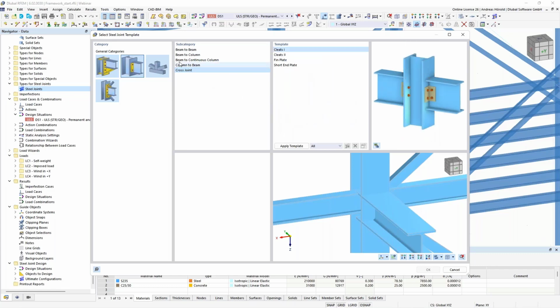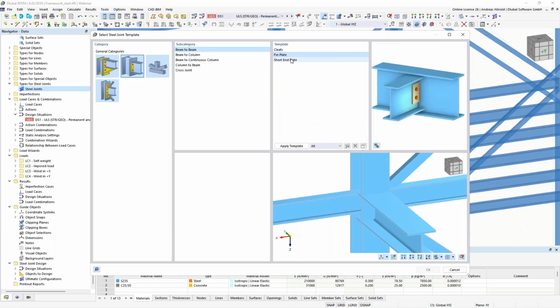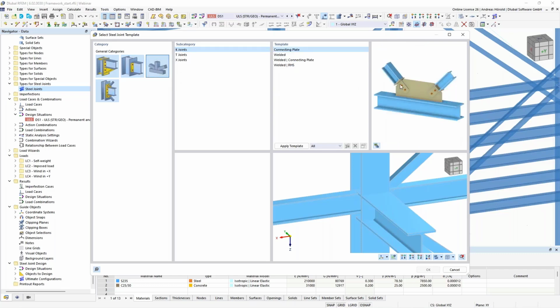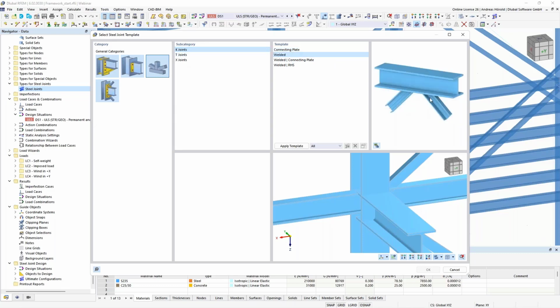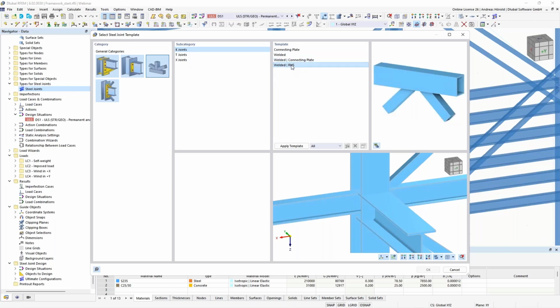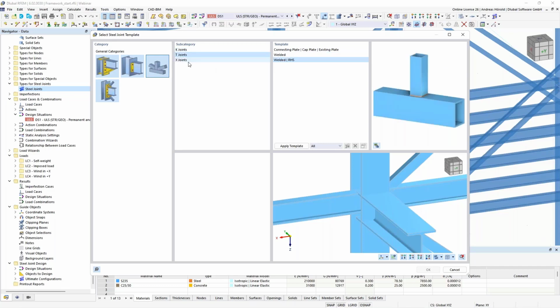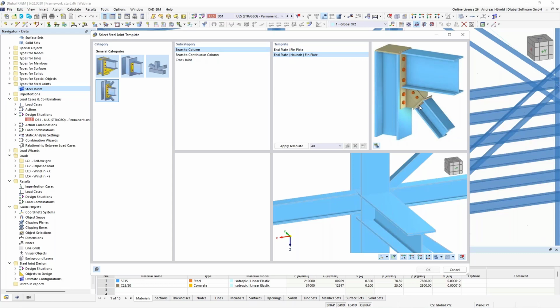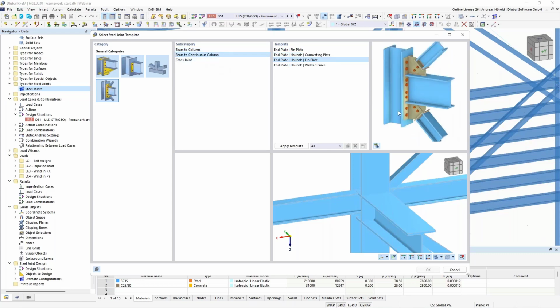Okay, I will show you some pinned connections: beam to beam with cleats, thin plate, short end plate, beam to column, the same, cleats, thin plate, short end plate, and so on. Trusses, you can use that for diagonals or for bracings. The key joint, welded, such a connection. Also for bracings to use welded, it's quite new. The rectangular cross sections with a weld, T-joints, X-joints, and so on. Then last but not least, the bracings. Similar connection, such a connection. Okay.